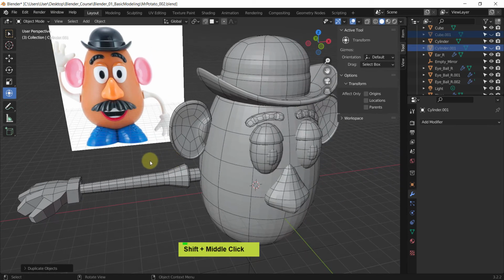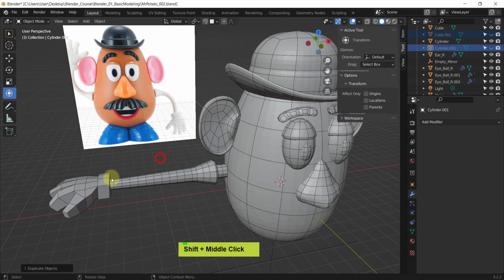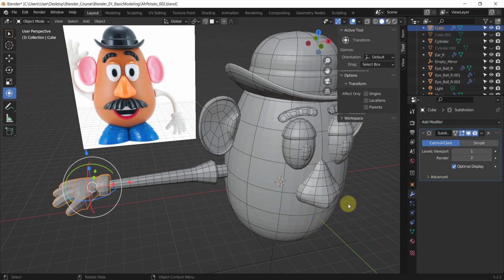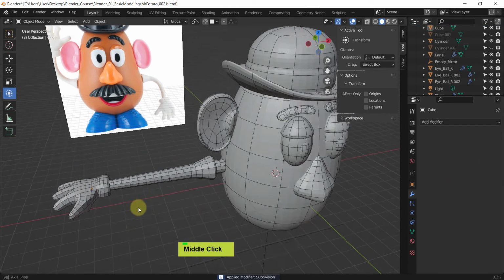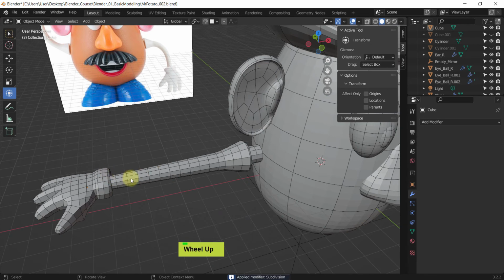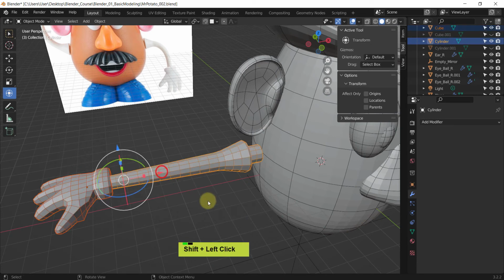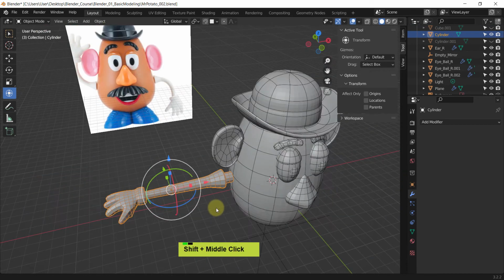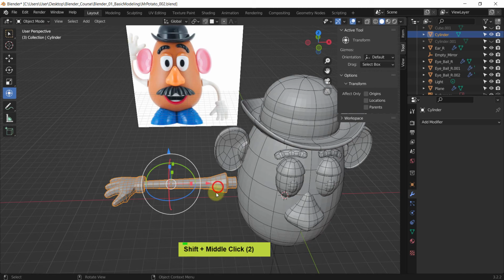Saving is also good, but this way you have everything in the file and you just don't go crazy. And adding subdivision 1, level 1, and pressing Ctrl A, that will apply. And now we have a somewhat matching resolution. So this guy and this guy are selected, and Ctrl J is pressed to make sure everything is in one. Okay, now how to bend it?